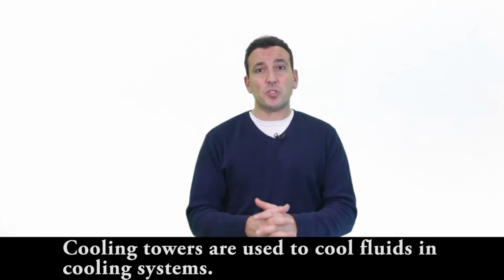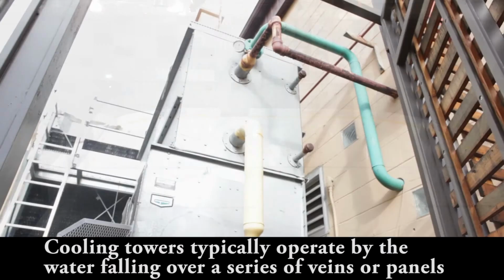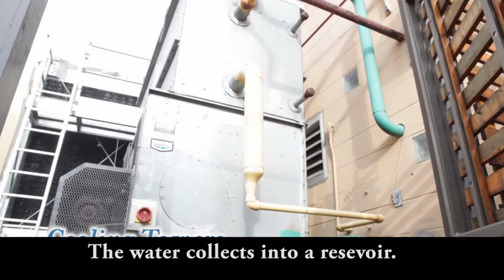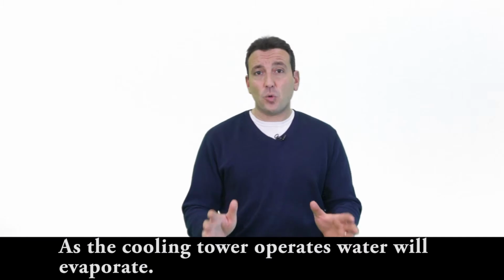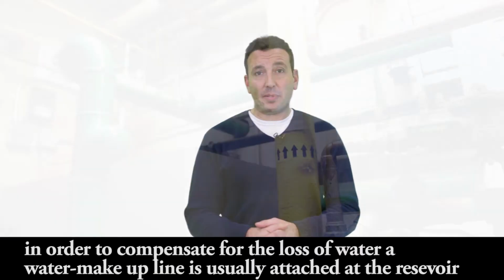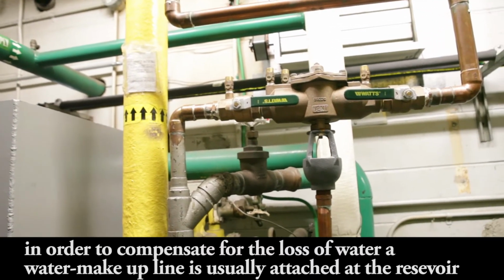Cooling towers are used to cool fluids in cooling systems. Cooling towers typically operate by the water falling over a series of vanes or panels. The water collects into a reservoir. As the cooling tower operates, water will evaporate. In order to compensate for the loss of water, a water makeup line is usually attached at the reservoir.